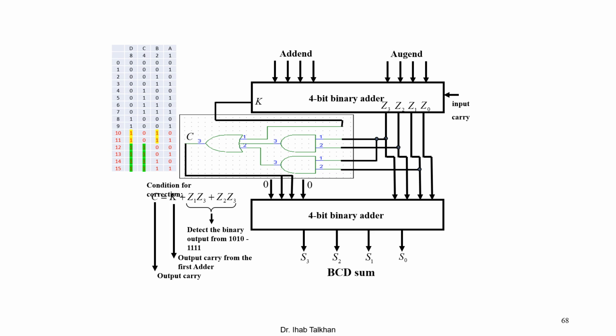You can see how to do that. In the second input, we have two fixed lines, the first and the fourth, which are 0 and 0, and the two in the middle are connected to the output of an OR gate. Whenever C equals 0, you get 4 zeros. Whenever C equals 1, you get the number 6, which is 0110.